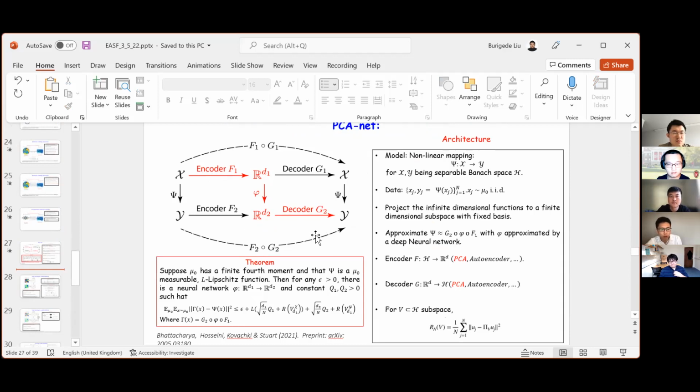Oh, I see. So over here, when you do the order reduction, do you use PCA, principal component analysis, to reduce the dimension? Yeah. I see. So the X is the input you get from all the FE Gaussian nodes, that is the data. In that case, if you use a different mesh and get a different number of Gaussian points, then the PCA will probably give you a different dimension of the data. Is that something? That's the thing, yes.